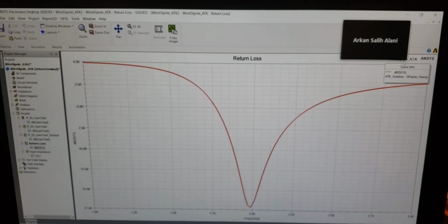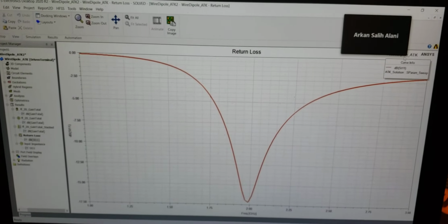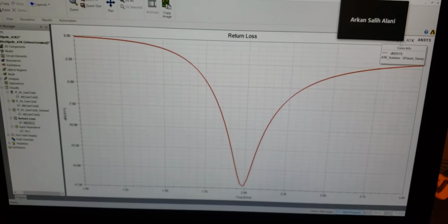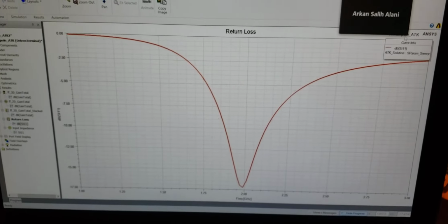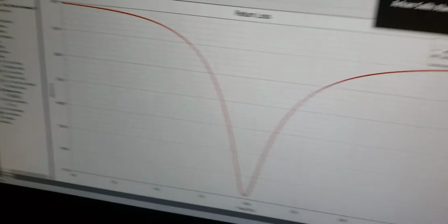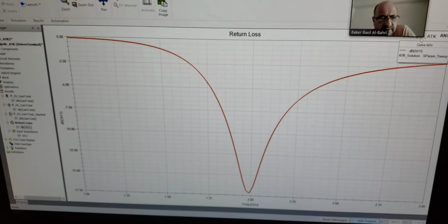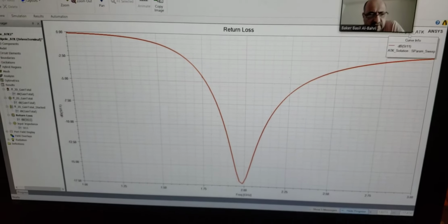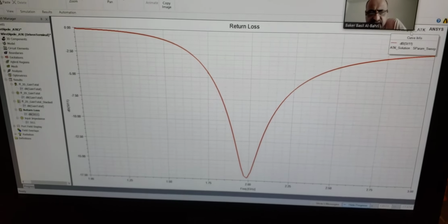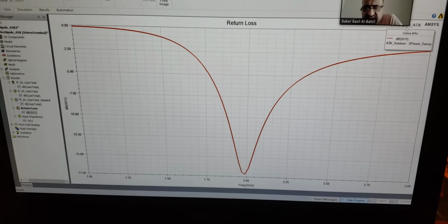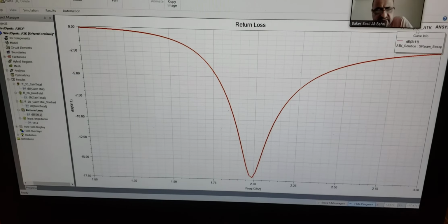They told us to zoom in or something like that to calculate it accurately, but I still don't know how to do it. To find it, you can zoom in and find the value, and you put it in your report. Put whatever the value of the return loss is at the frequency where your return loss has its minimum, or provide 4 significant digits.